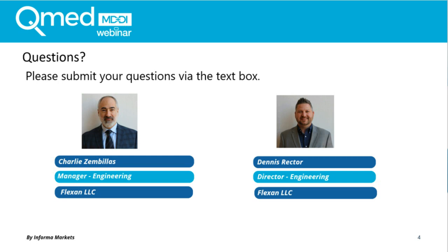Our next question asks, what's the most commonly requested hardness for tubing? I would say 50 or 60 Shore A is the most common durometers that we extrude.